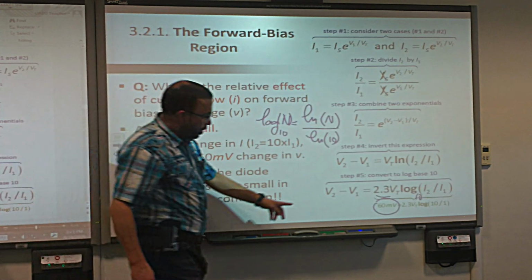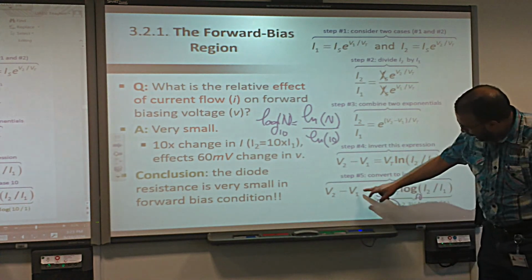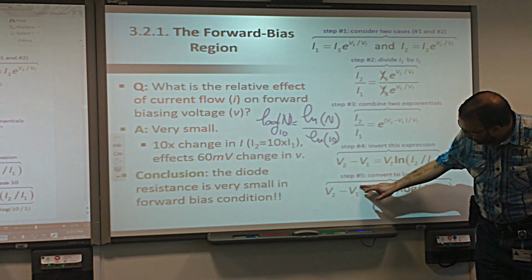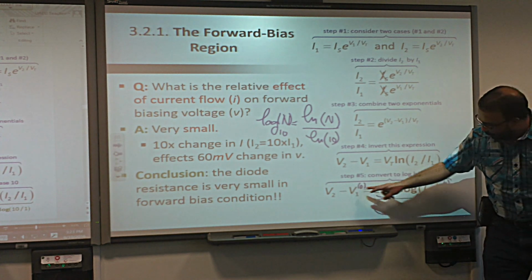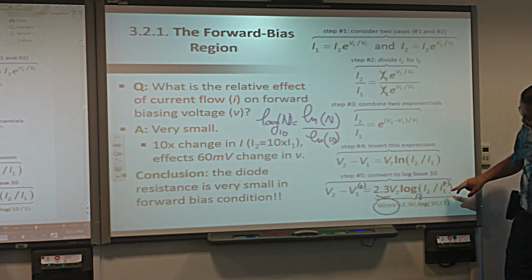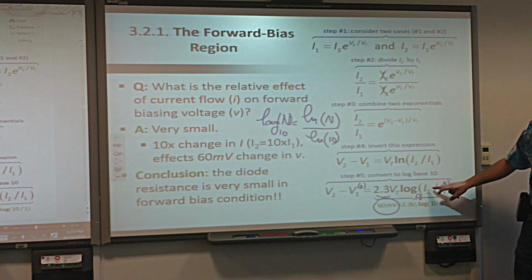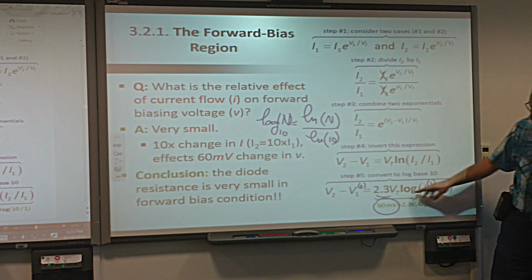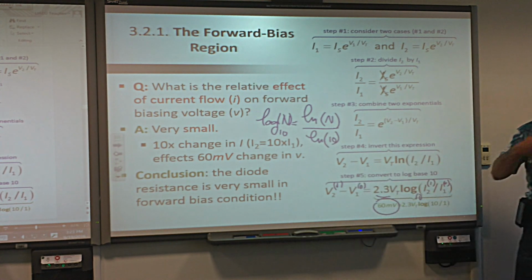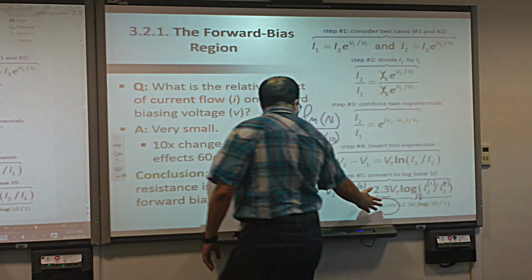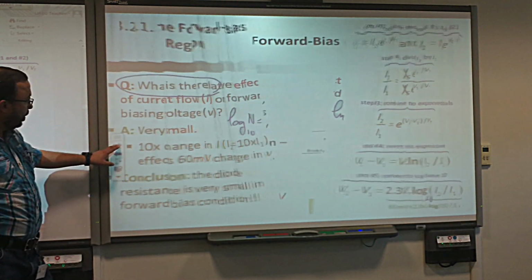So what you found here, V1, will be the first V and I1 the first I. These are the coordinates of the first point that we know. And I2 here will be the current that I just calculated. So from here, what do I need to know? I need to know this. I will find V2, the new voltage across the diode. This is the equation that we will use for the iterative solution.